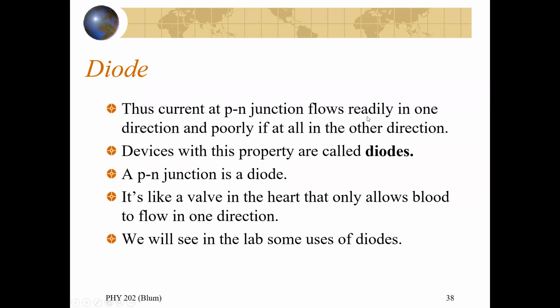Okay, so this thing that I've been calling a PN-junction, and that's the proper name for it, because that's what it is. You brought some P-doped stuff next to some N-doped stuff at a junction, but it's also called a diode. If you're talking about what it's made of, you call it a PN-junction. If you're talking about what the device is, then you call the device a diode. PN-junctions are diodes. Not all diodes are PN-junctions, because you could make a diode out of a vacuum tube. A diode just means here's my role in a circuit, whereas a PN-junction is how I make the device that has that role in the circuit.